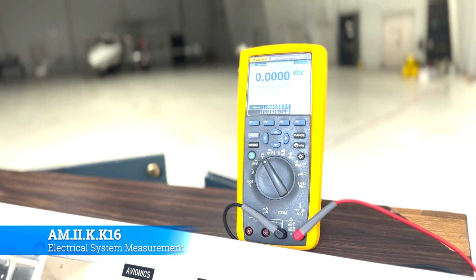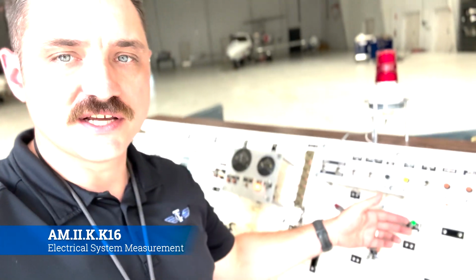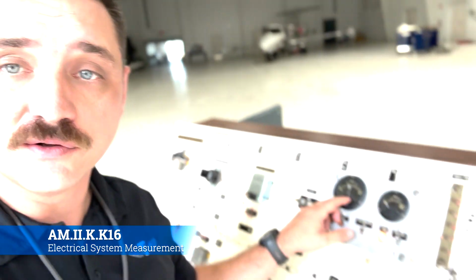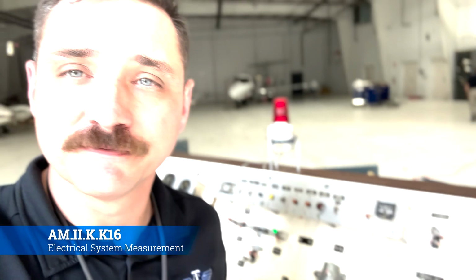So let's start trying to work our way back and see if we can find where the power disruption is. Kind of a good rule of thumb whenever you're doing this type of work is to look and see what all is actually working, so you can quickly eliminate some things. In this situation, we see that we've got power going on to the main bus. We don't have the alternator on, so we don't have to worry about that, but we do have battery volts, so it's not an under voltage situation. We have power going on to the lights. We know that circuitry works, so it's really just going to be localized into our avionics bus over here.